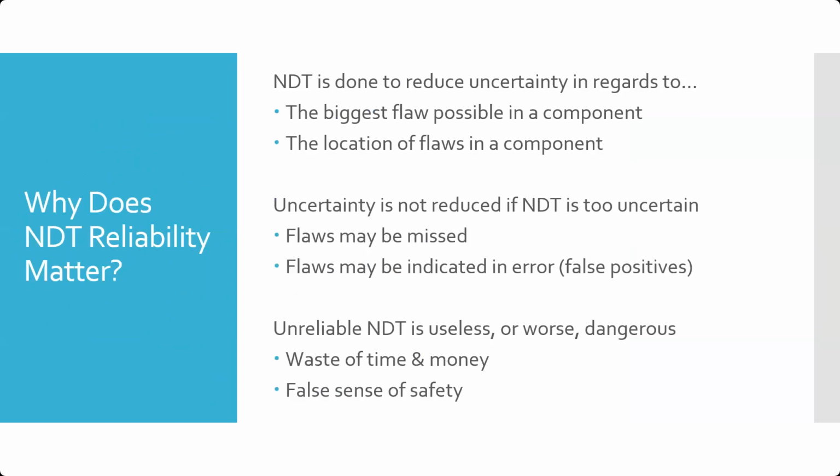So why does it matter? Why does NDT reliability matter? So we perform NDT to reduce uncertainty in regards to the biggest possible flaw that may be in a given component, as well as the location of the flaws in a component. And if NDT is too uncertain, then the uncertainty for an inspection or an uncertainty about a part is not reduced. And flaws can be missed, or maybe there may be indications made in error, known as false positives. What this ultimately means, though, is that unreliable NDT is useless, or often worse than useless, it becomes dangerous.